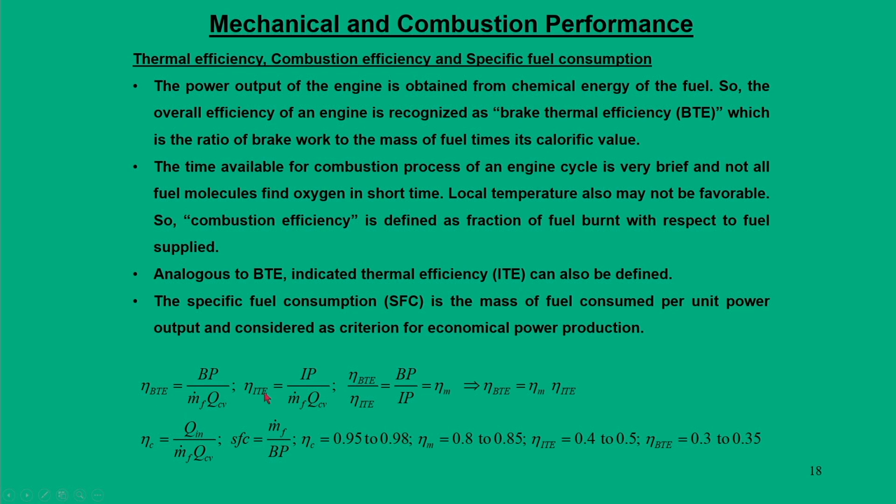In a similar sense, we can also define the indicated thermal efficiency, which is equal to IP divided by m dot f into QCV. The ratio of brake thermal efficiency to indicated thermal efficiency becomes the mechanical efficiency. We should not get confused between thermal efficiency and mechanical efficiency. Mechanical efficiency is between brake power and indicated power, while thermal efficiency is between brake power and the fuel heating value. So, these two terms should not be confused.